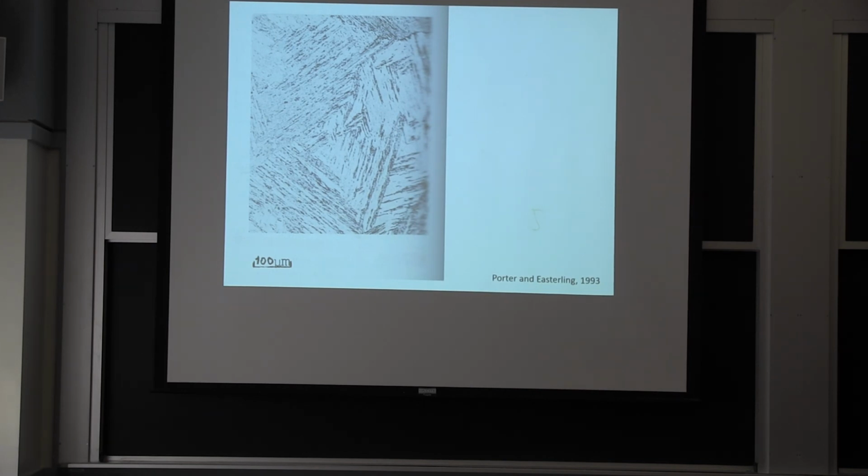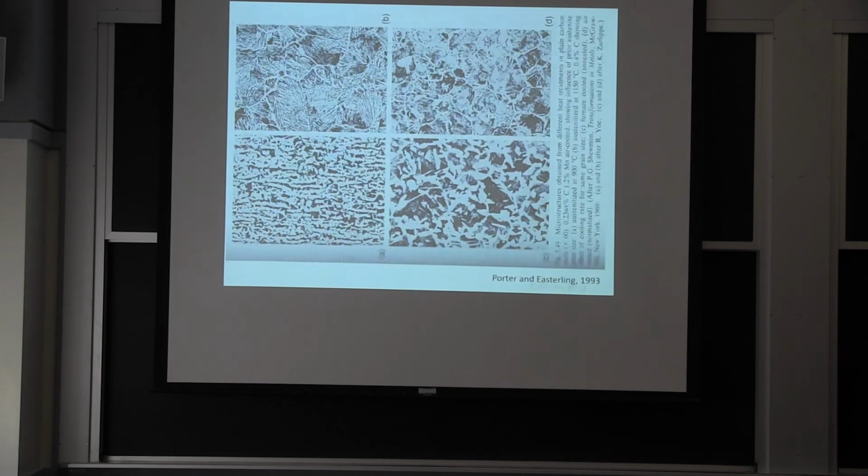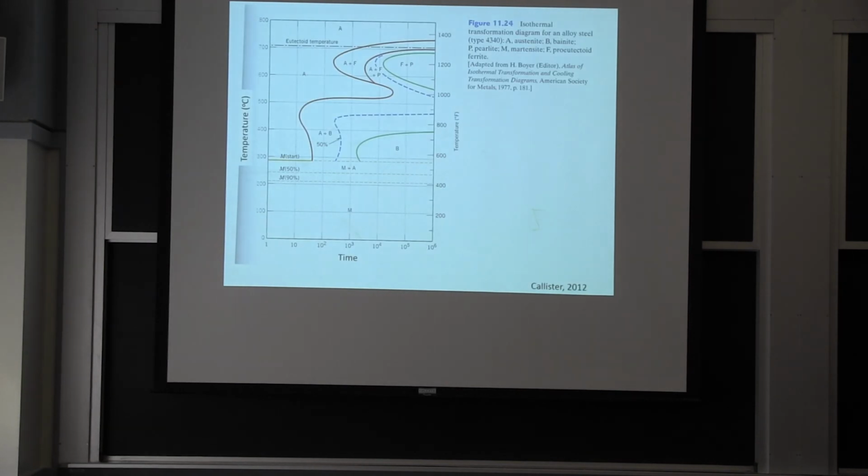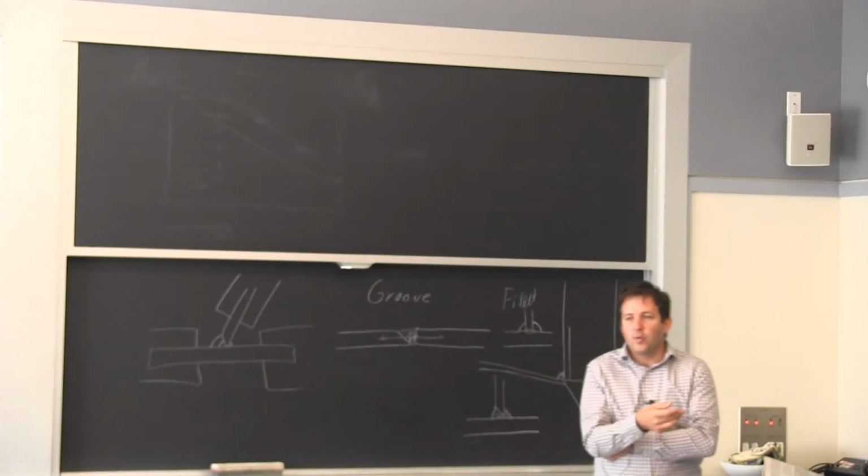The 4340, that example I was looking at, if you're going to try to weld this, you need very sophisticated procedures. You need to preheat the steel, and a lot of times you need to go after what the preheating does, it's preventing you from forming cracks.